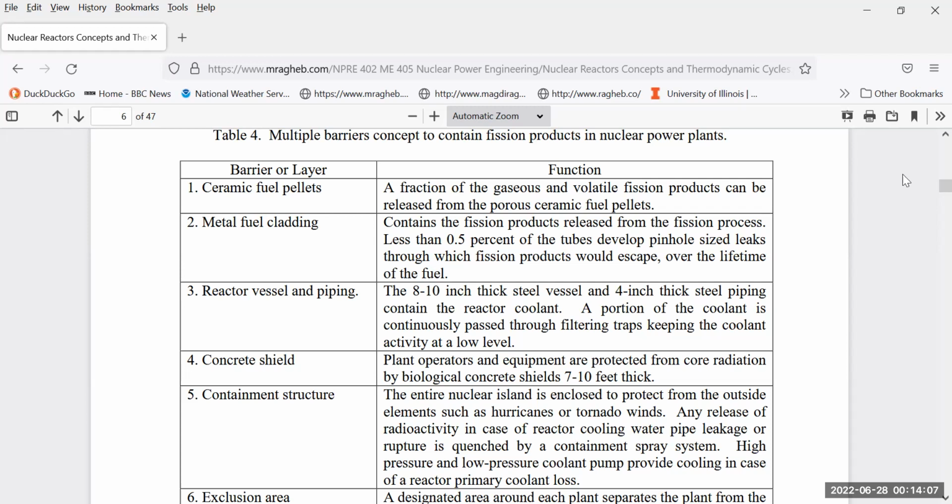So we are using in fossil fuel production open systems for the disposal of the product of combustion. And in addition, when we burn coal, we release the particulate matter to the atmosphere, and some of it contains radioactivity from uranium. In contrast, for nuclear energy production, the amount of waste is very small. A typical 1,000 megawatt power plant can produce maybe waste the size of a desk, 1 cubic meter of high-level waste every year. So we have the luxury here of being able to contain it.